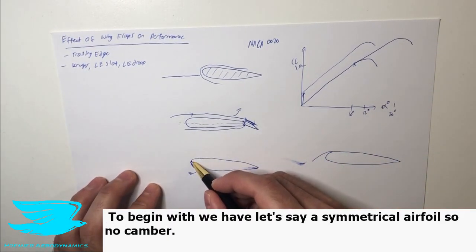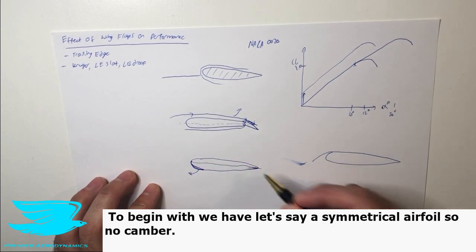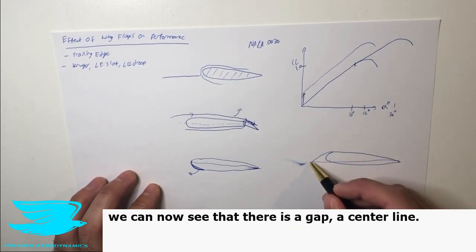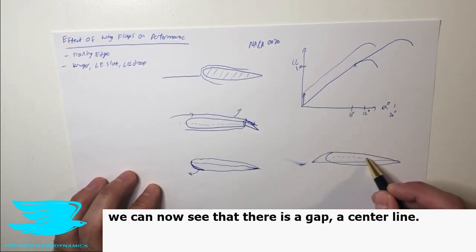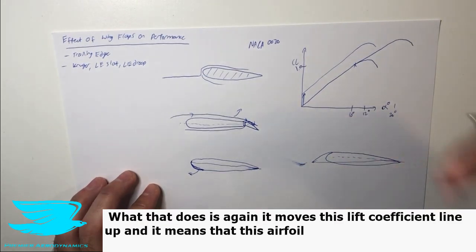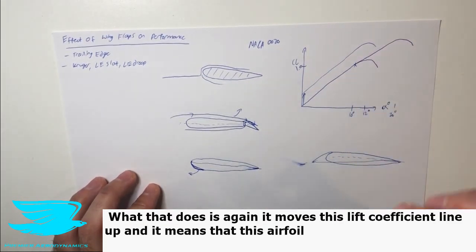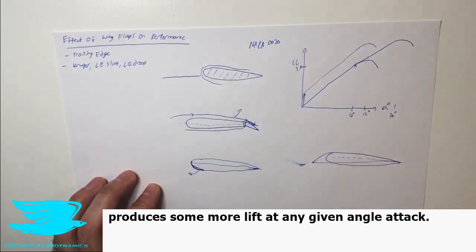To begin with, we had, let's say, a symmetrical airfoil, so no camber. But now if we were to draw a center line between the leading edge and the trailing edge, we can now see there is some camber. What that does is, again, it moves this lift coefficient line up, and that means that this airfoil is producing more lift at any given angle of attack.